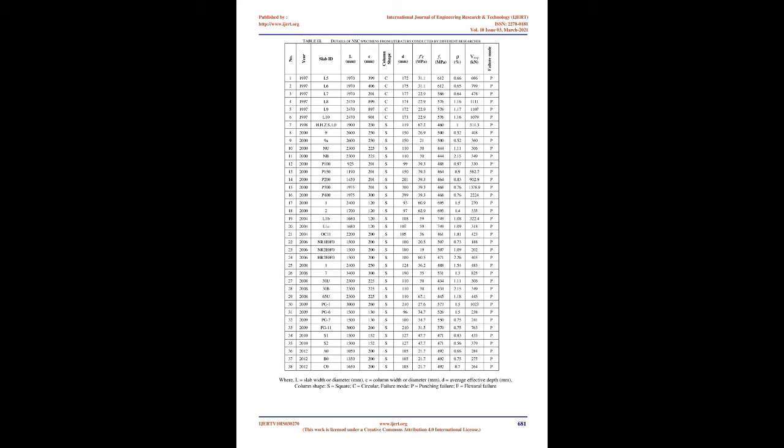Investigations showed that the main variables affecting punching shear strength are concrete compressive strength, f'c, flexural reinforcement ratio, average effective depth, d, and column geometry, critical perimeter b0. These four declared variables have the most significant effect on flat plates without shear reinforcement.